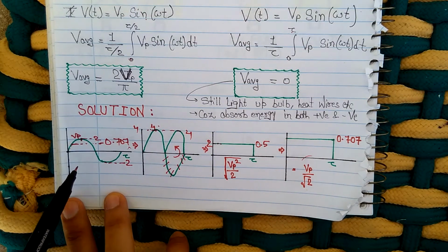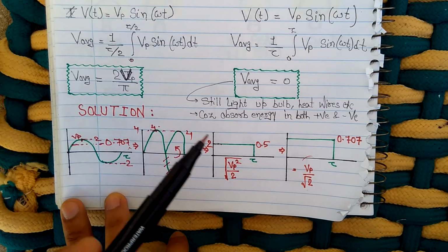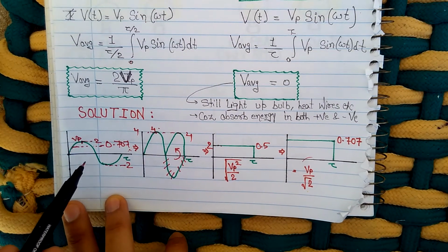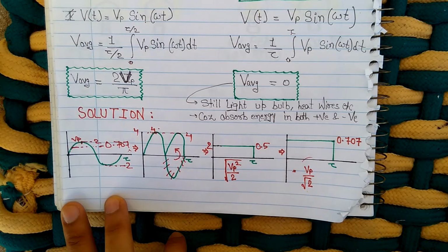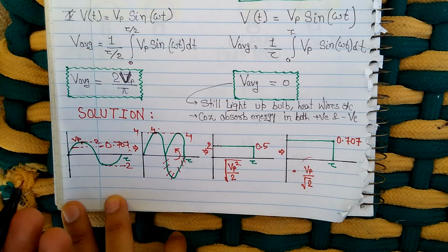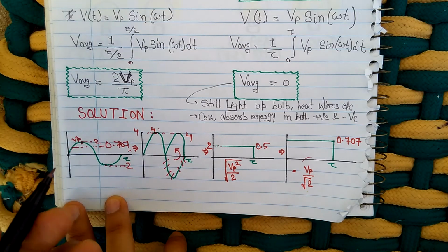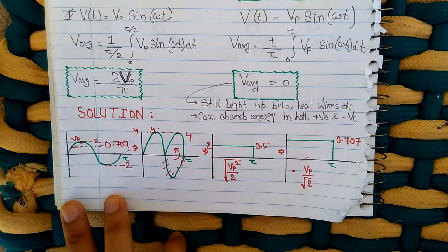So what we did, we first squared this, then found the average, and then took the root to undo the effect of the squaring. Now this thing is called root mean square. This was introduced to find out the absolute value of some alternating waveform, because AC was very popular and you have to find out some absolute value, so the RMS value became popular.